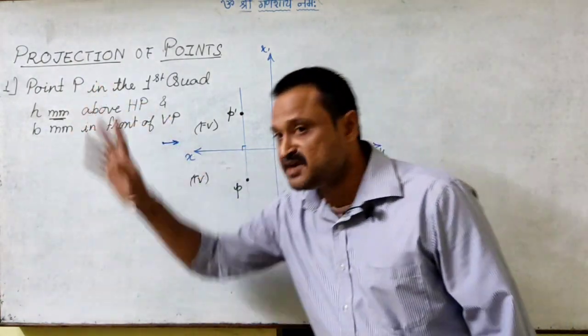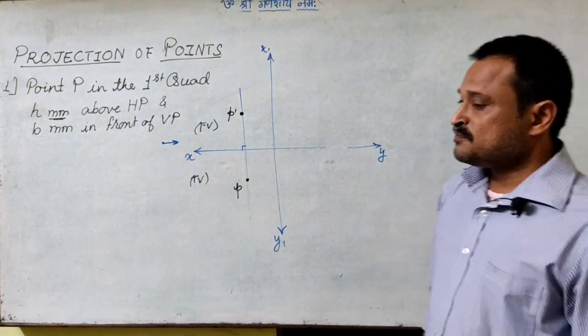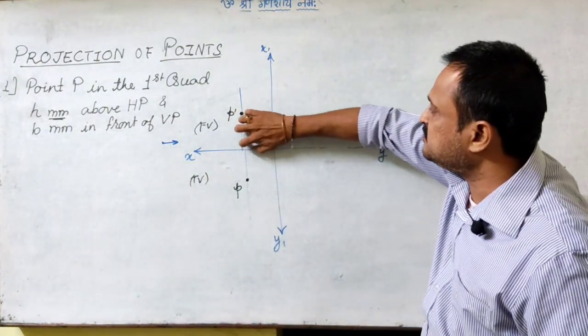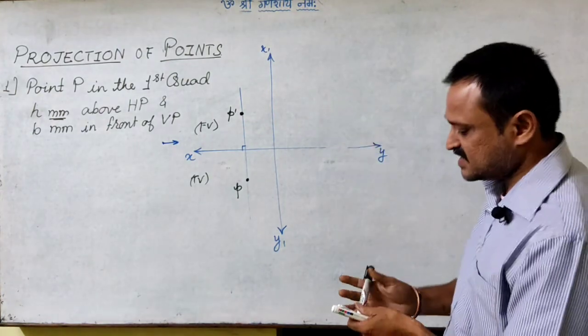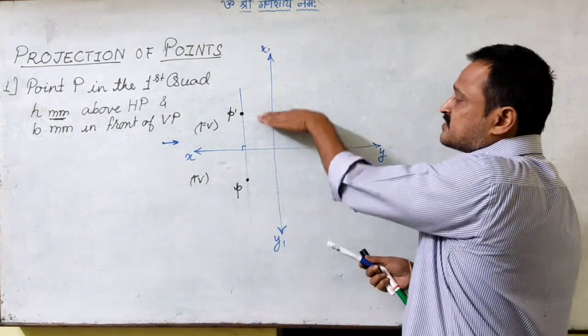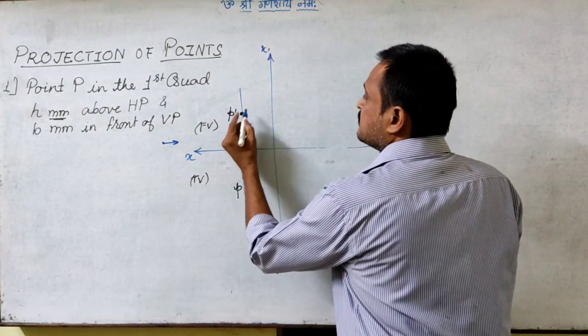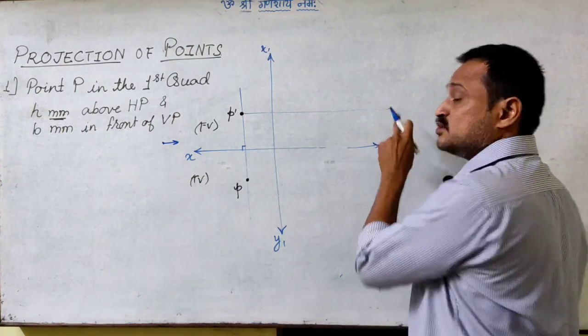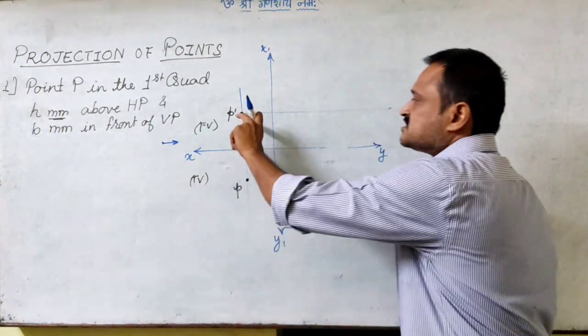So both H and B are visible to me. Now when I am opening this, the height is not going to change. So I can simply drag this dimension to this area. So I can draw one line parallel to the reference line from the height of this point. I'll call this the locus of point P. So it is the same height.